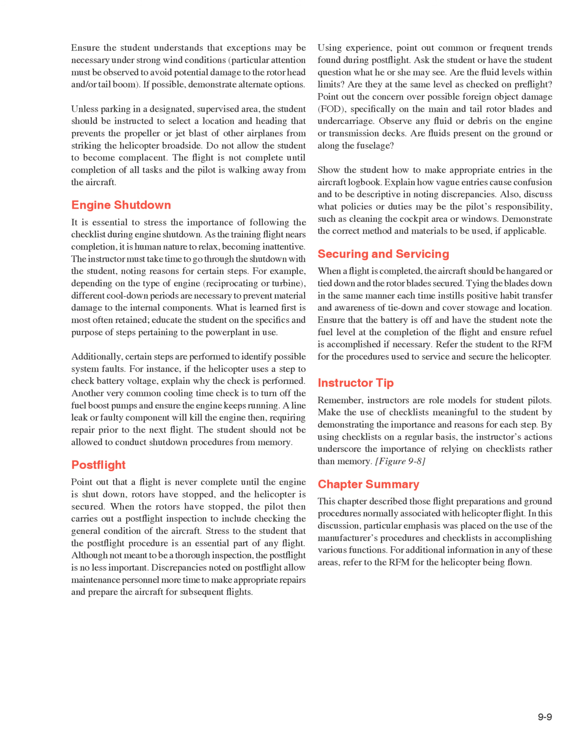Using experience, point out common or frequent trends found during post-flight. Ask the student, or have the student question, what he or she may see. Are the fluid levels within limits? Are they at the same level as checked on pre-flight? Point out the concern over possible foreign object damage, FOD, specifically on the main and tail rotor blades and undercarriage. Observe any fluid or debris on the engine or transmission decks. Are fluids present on the ground or along the fuselage?